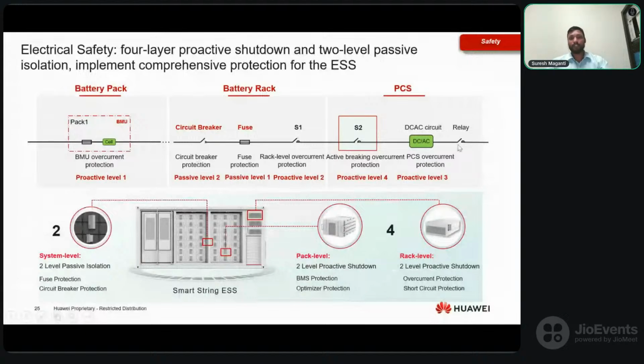That is high voltage that comes, which will affect the PCS performance. At that time, if the battery storage system is almost discharged, maybe at SOC level 5 or 10%, and it is in the discharging function, if any HVRT comes, in a traditional or industry battery storage system there will be backfeed towards the battery storage system. That is really a big problem for the battery storage system, and it will really affect the performance of the converter as well. So these are the various levels of protection within the storage system.